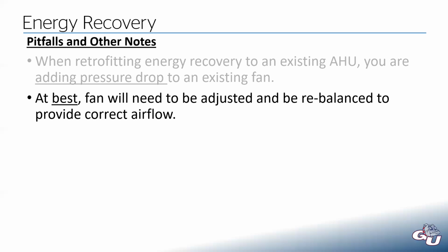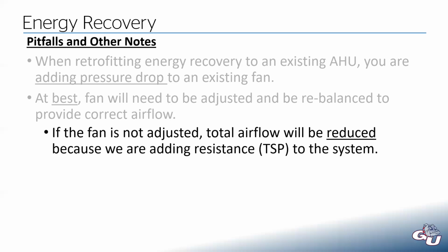Normally, when you do a construction project, you buy all the fans you need, and then you have to hire a balancer who goes out there and makes sure all of the fans on that system are moving the amount of air they're supposed to. So if you go in after the fact and put this new energy recovery device on an existing fan, and the fan's not adjusted, then you're going to reduce the total airflow because you're adding resistance to the system. And if you don't rebalance the fan, that will result in less airflow. So that's best case condition.